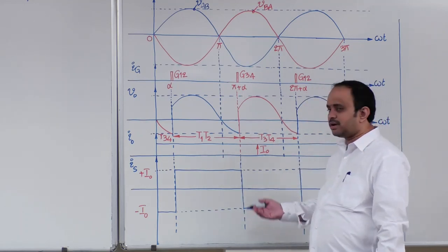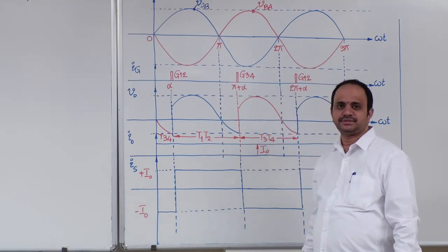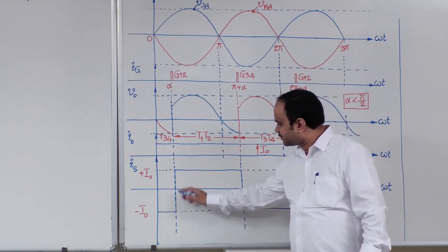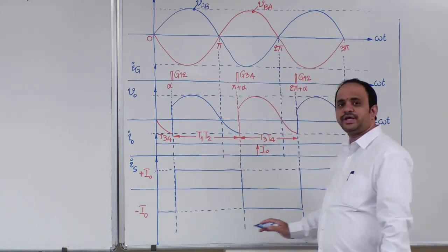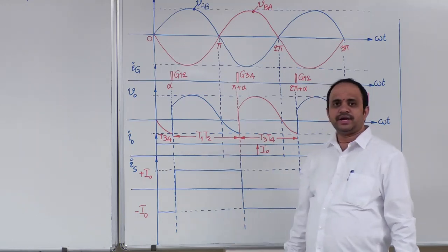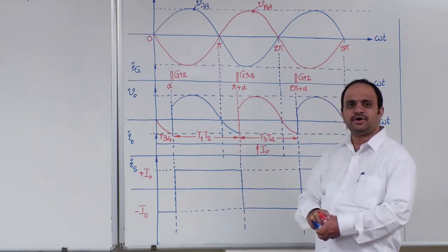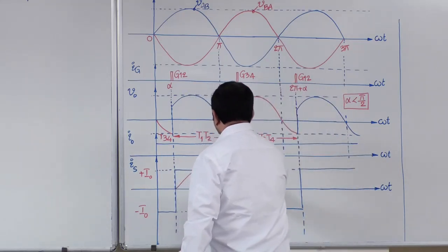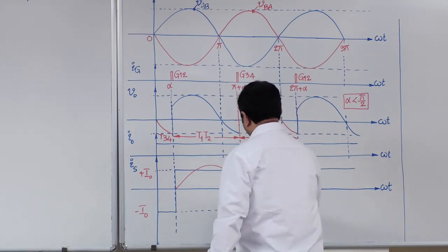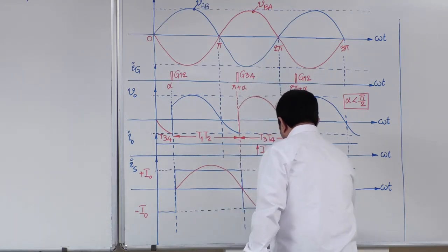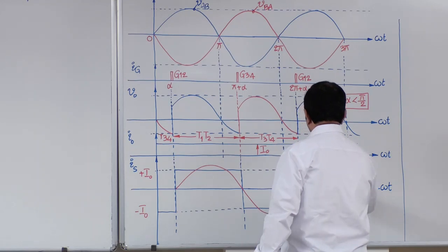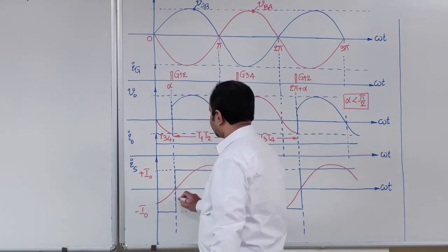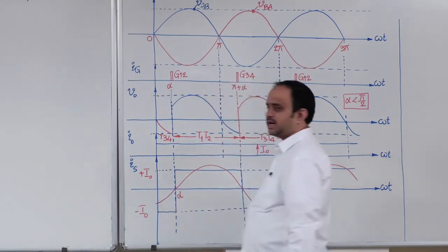If you recollect from the beginning lectures, I hope lecture 2 or lecture 3, for exactly the same waveform we did Fourier analysis. For this particular waveform, if you recollect and draw the fundamental component, it will be something like this. The fundamental component starts from omega t equal to alpha, the instant where this square waveform started on the x-axis. This angle is alpha.